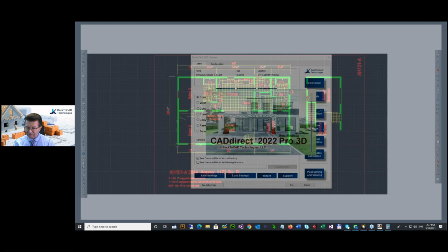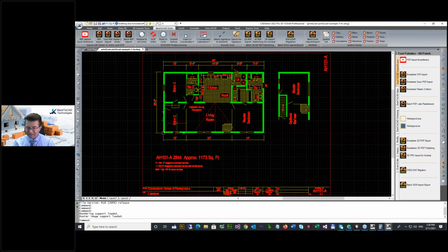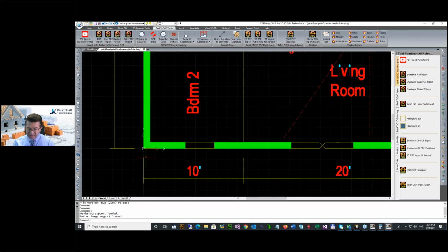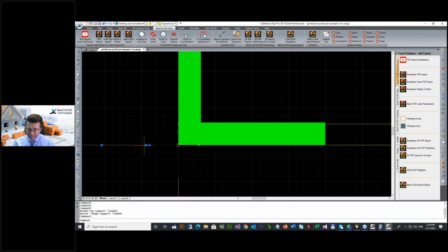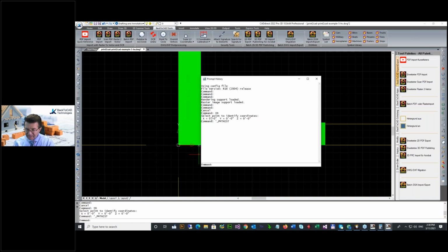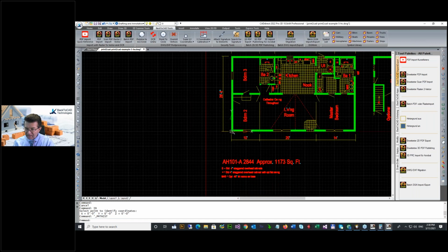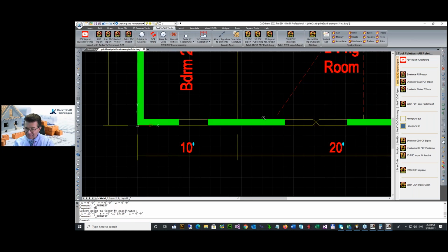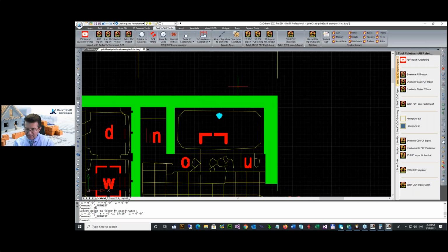And let me check here not only the quality of the drawing. You see now this is a calibrated drawing. You can see the zeros here, but look what we did. The calibration moved the dimensions here exactly. If you ask here with ID the coordinates here, you see this is exactly 0, 0. Okay, and now if you ask with ID this coordinate, this is exactly 10. Can you see? And if you ask now with ID for this coordinate, this is exact.